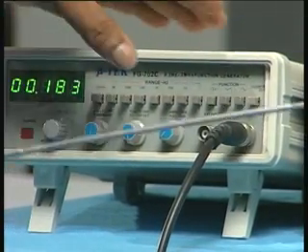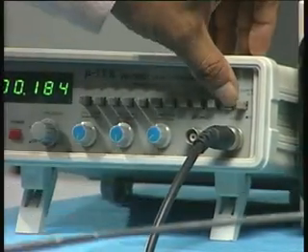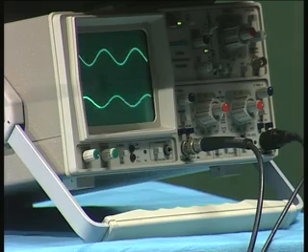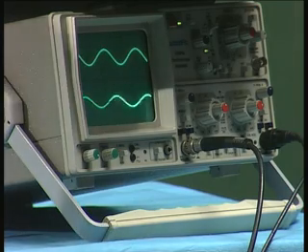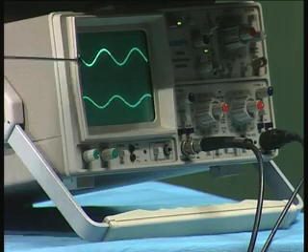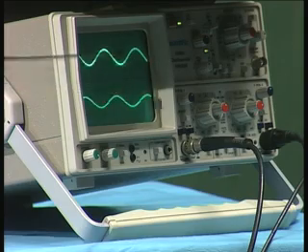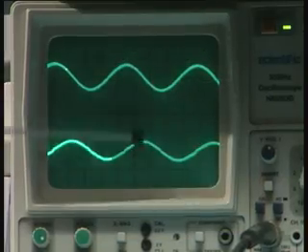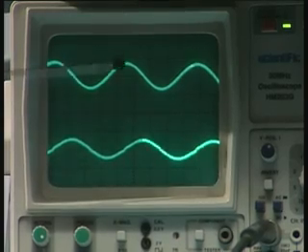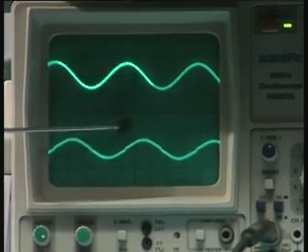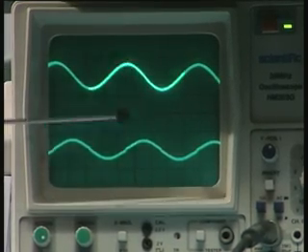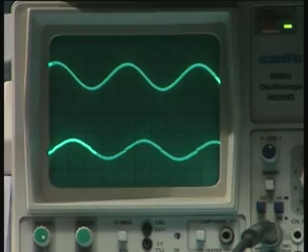If I give a sine wave, you find both of them are sine waves, because one is a sine wave, the other is actually a cosine wave. Therefore there is a difference of about 90 degrees in phase, which cannot be very precisely seen here, but you can certainly see that there is a phase difference. If you look at the corresponding peak positions, you find they are not in the same vertical line.